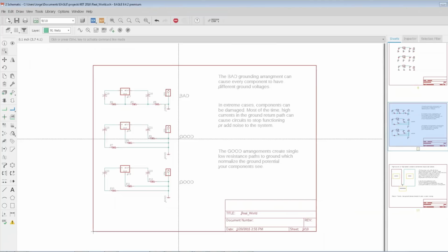And if there's anything in the way, then that's going to change the impedance and it's going to add a little bit of noise. So if you have a via in the way of that clean return path, then the current's going to have to go around the via, and that's going to change your impedance. Okay? So those are the three fundamental concepts we want to take away from the webinar today. And those are going to form a building block for future webinars on signal integrity.